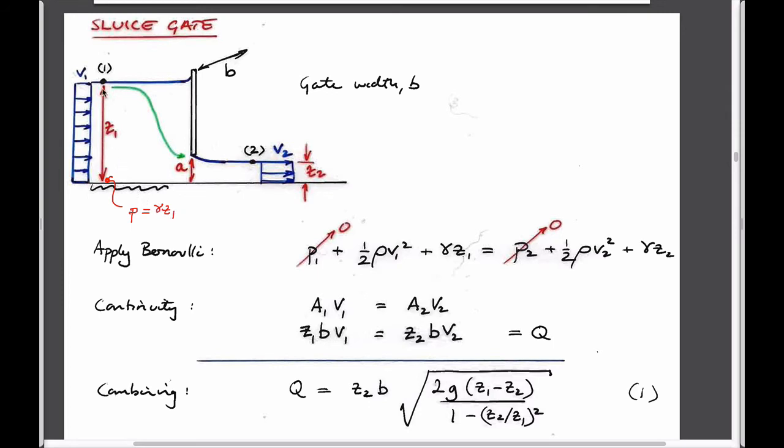And so that would be one way, to measure pressure very easily and use that to convert for a head magnitude. Sometimes that's used in wells, in oil wells and water wells. You measure pressure, and you can calculate the column height of fluid in a static well. And if it's flowing, you could also calculate the change in the pressure that you have because of the driven flow in the system as well.